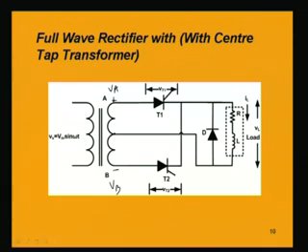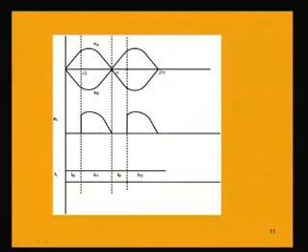When the current flows through this load, the voltage across this load will be equal to this VA when this T1 conducts. So, that is happening here. When this T1 conducts after angle of alpha, the voltage across the load will be following this VA.